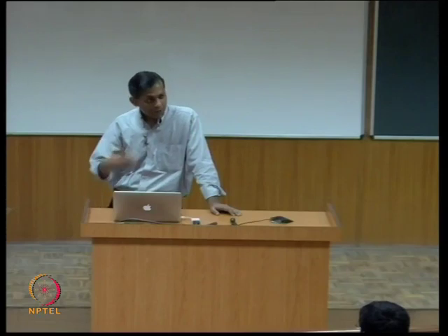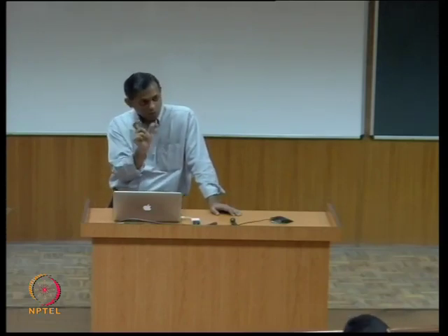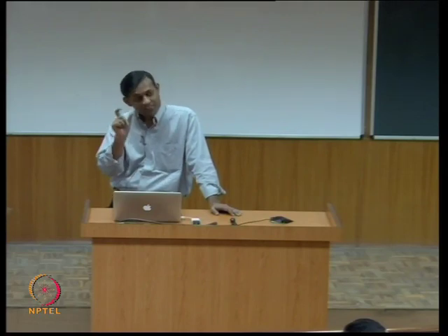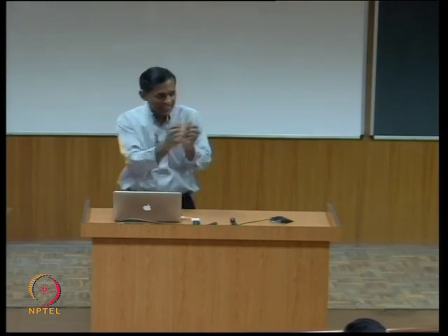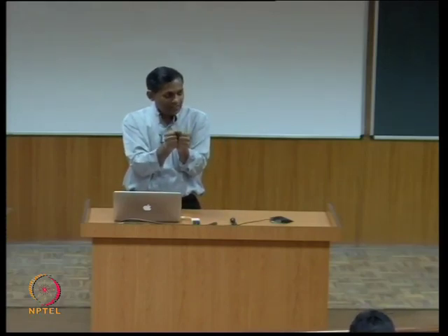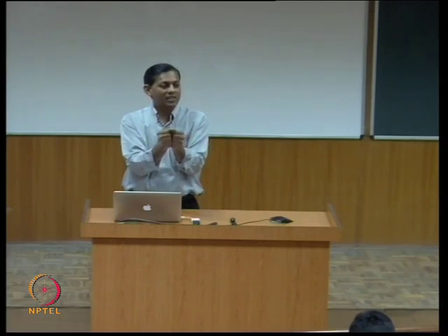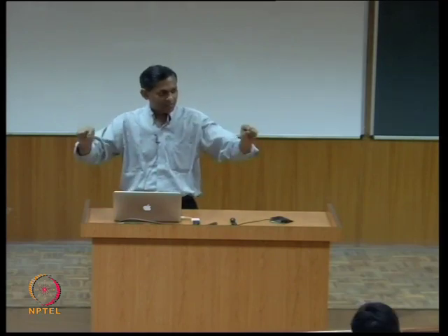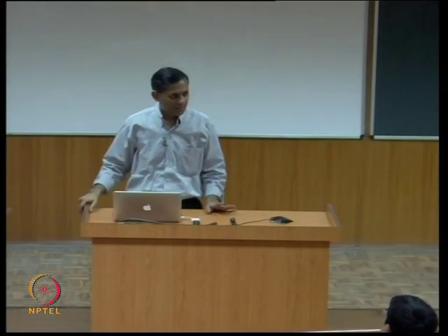Will there be enough stuff for all the members in a grid to work in parallel? If you've got only a block, it always runs on a single SM. We are dividing the grid into blocks. A block is a tightly integrated group of threads, and that tightly integrated group of threads must run on a single SM. A single SM is just a 16 wide SIMD processor.